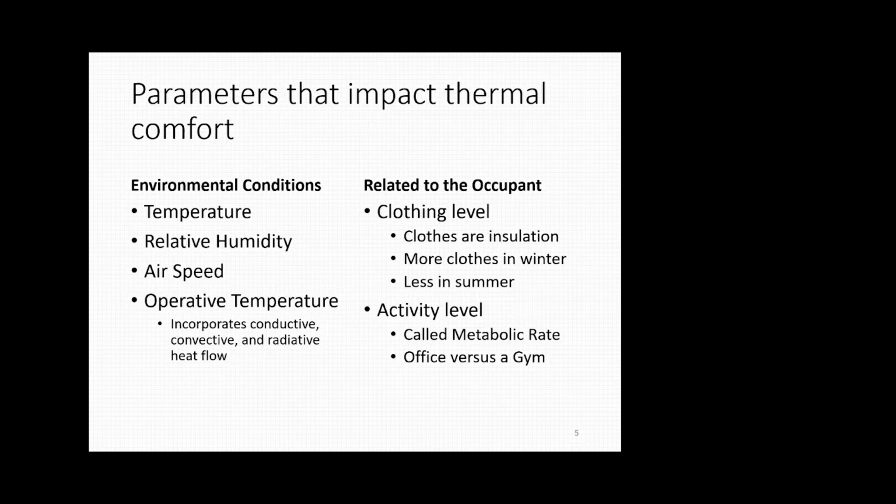So where humidity condenses, if you have super humid air, then the water is going to condense at a higher temperature. So like if you have a really humid attic and it's vented and your house isn't sealed that well and you're running the air conditioner in your attic, right? If your ducts are not very well insulated and there's really humid air in your attic, what's going to happen? Your ducts are going to sweat. So that's something that you don't want to happen. So the humidity level is something that we have to control.